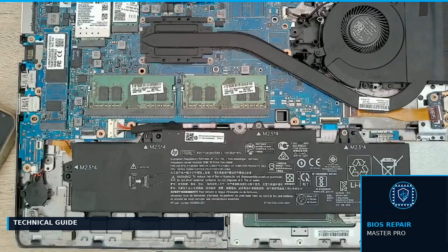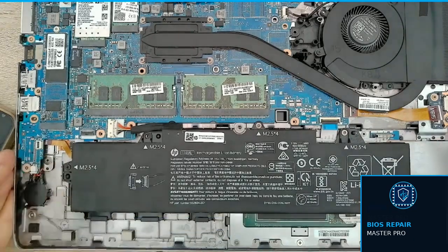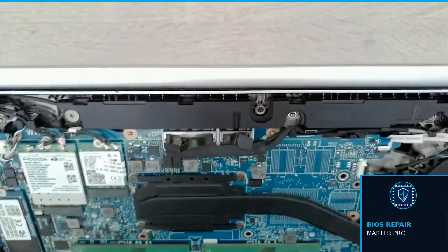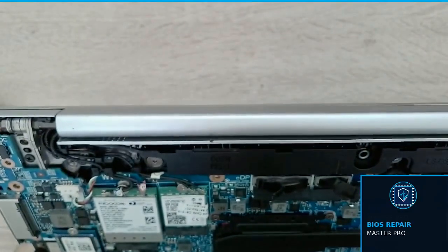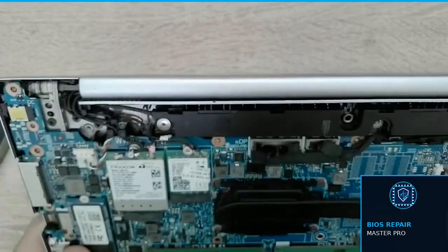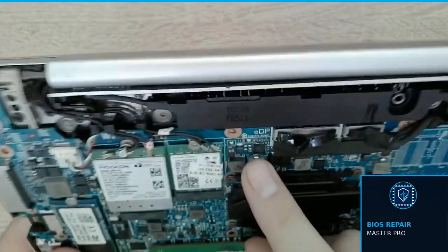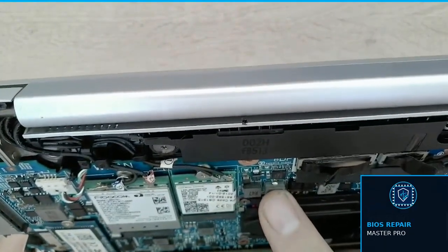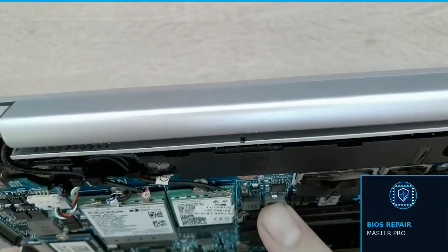In this demonstration, we are examining an HP 850 G5 laptop that initially showed no power-on response. After opening the system, we can see marks around the processor power coils. This observation may suggest a problem in the power delivery circuit, but a visual inspection alone does not confirm a short circuit. The previous BIOS flashing attempt was unsuccessful.